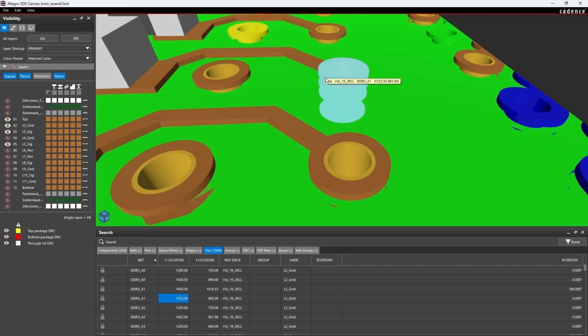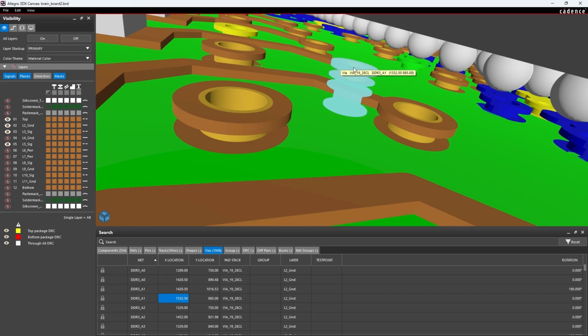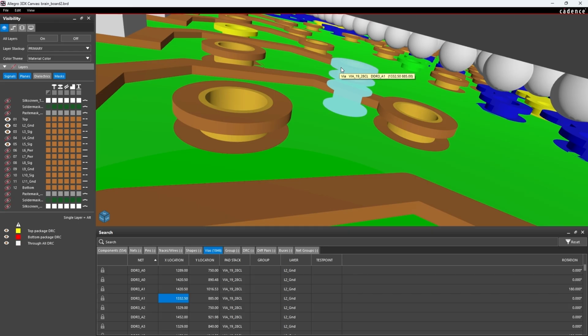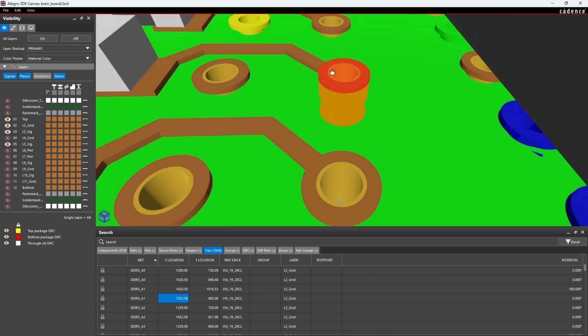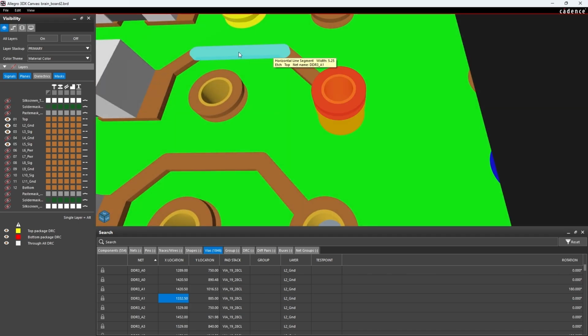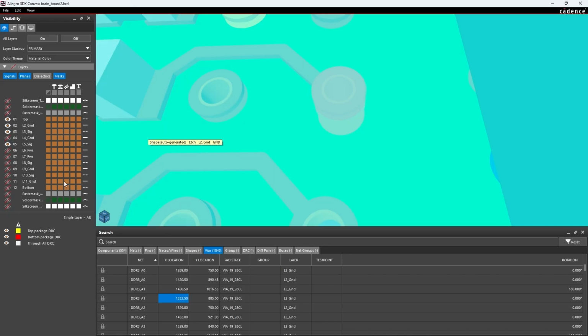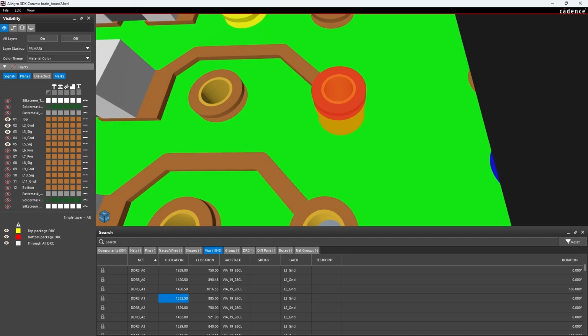That can count to have the signal coming out of that via, the electromagnetic field specifically, have something immediately coupled to be its return reference. That way the field remains contained and stays right underneath this track. If you haven't seen my video on how to do return path simulation, you may want to check that out or attend any of my discussions or lessons, like in a webinar.